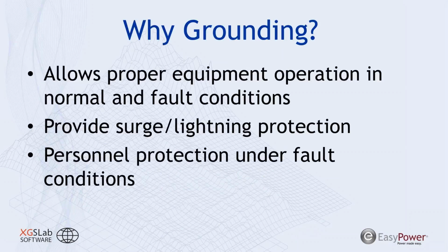So why are we doing grounding? One, it allows proper equipment operation in normal and fault conditions. It also provides surge and lightning protection. And this last bullet point, the personnel protection under fault conditions, this is primarily what we are considering when we're doing a grounding system analysis.